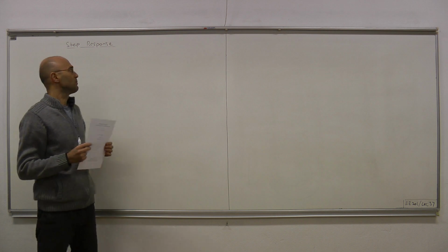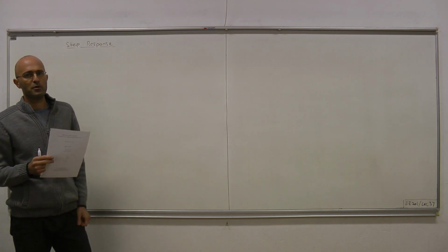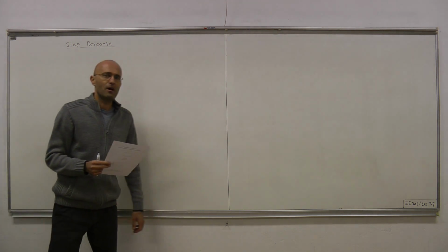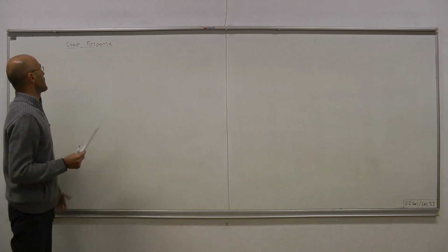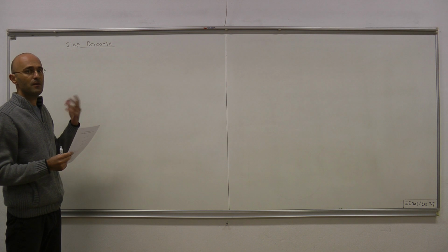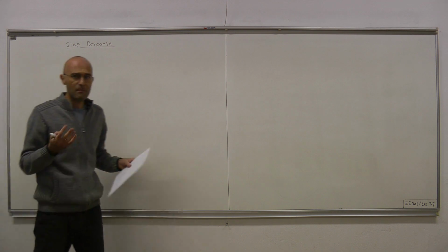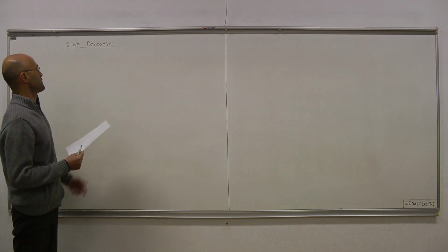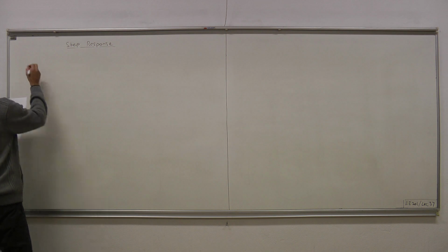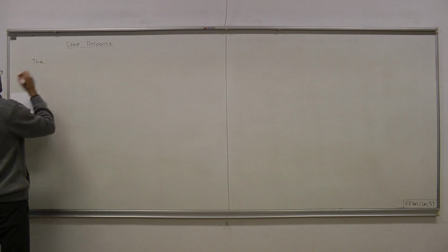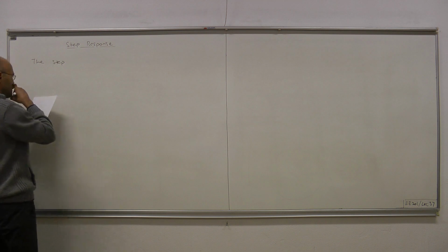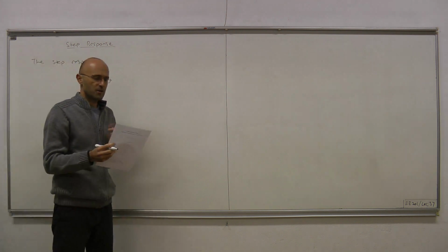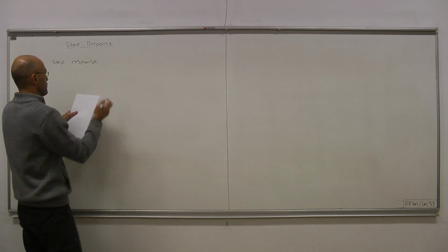We begin this lecture with the step response of a first order circuit. First of all, we have to be precise about what we mean by step response. So we have to define what this is, and step response in general is applicable not only to first order circuits but to general nth order systems. Okay, and what it means is the following. Step response is the zero state response for a unit step excitation. So the step response of a circuit